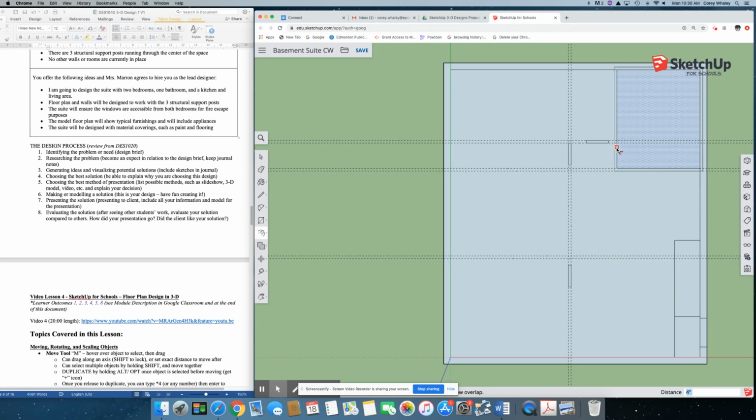And then I need to draw in that doorway right here as well, which I will with the rectangle tool. So the way that I did that, just so that it was exact, is I'll probably start it right about here. And then I'm just drawing out to start. You can see my dimensions in the bottom, but I want to make it exactly 2 foot 8. So I'll type 2 foot 8 inches, comma, 4 inches and click enter. And that gives us that exact dimension. And that works out pretty good.